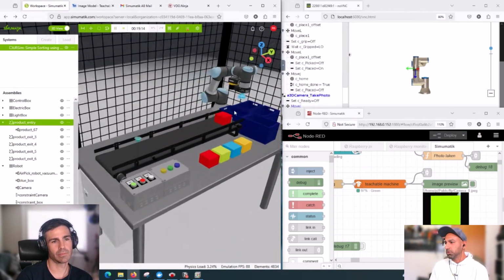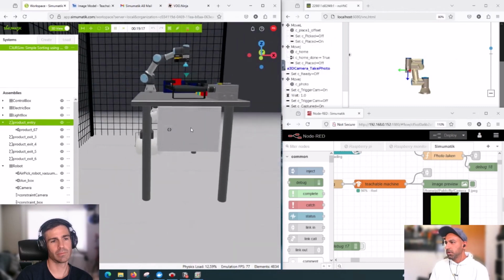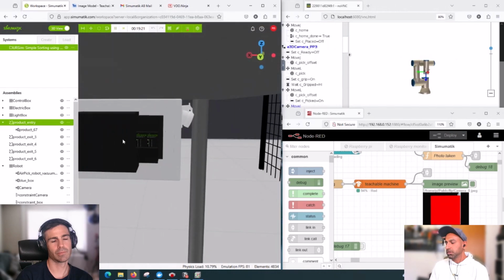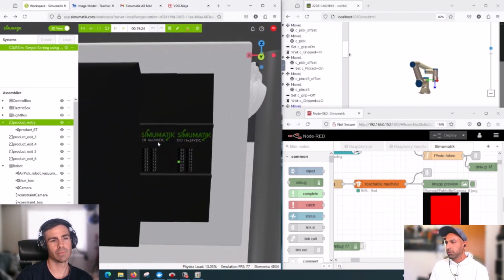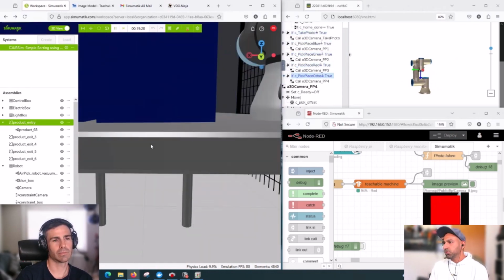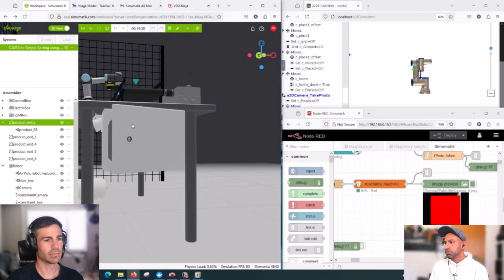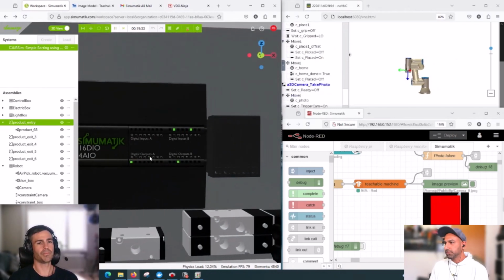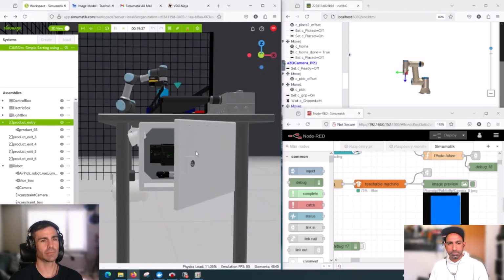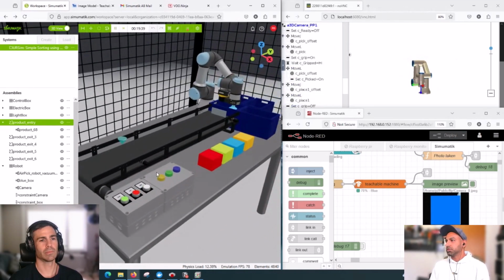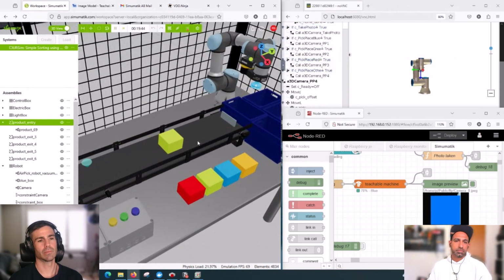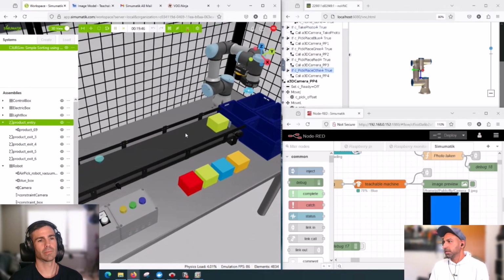So we also have a robot controller here, somewhere, I think on the backside. This black box is the robot controller, and these two are the robot IOs. The robot has its own input-output modules, and this robot IO is connected to the PLC IO, which is inside here. So the PLC is talking to the robot via digital IOs, sending the signal, like if the sensor has detected the object, and some handshaking between the PLC and robot.